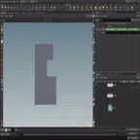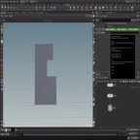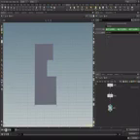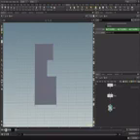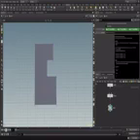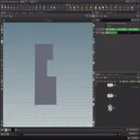We're going to do the same thing for the centroid. So let's type in centroid. We're going to select ourselves. There we go. And we are going to select the X direction. There we go. Now we have the centroid for the X direction. Let's copy this into the second and third channel and change those to Y and Z. There we go. So these are some very helpful expressions.